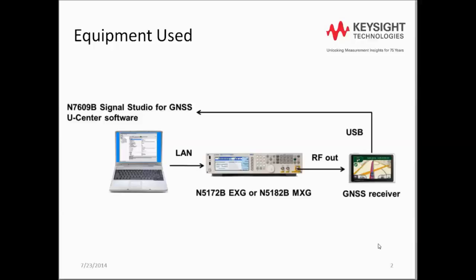The file used in the dynamic scenario was created from a trajectory recording I made using the u-blox GPS evaluation kit, which included a GPS receiver, antenna, and software. The u-center software has a record function that enabled me to record the messages from the u-blox receiver, including all of the NMEA messages. NMEA stands for the National Marine Electronics Association. You can use your own GPS receiver and software as long as you have the ability to record these NMEA messages.